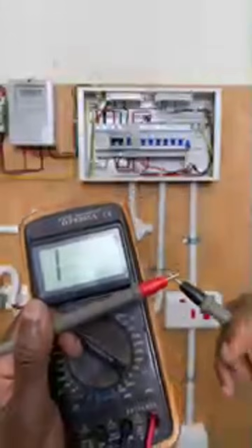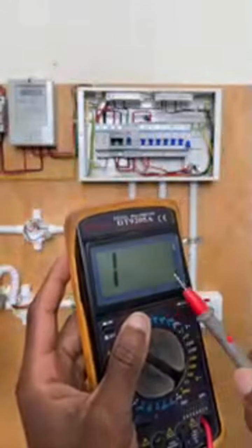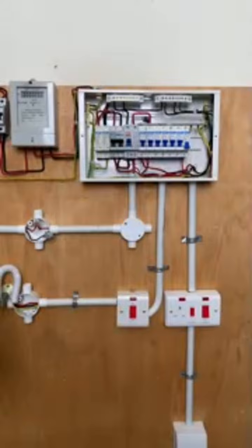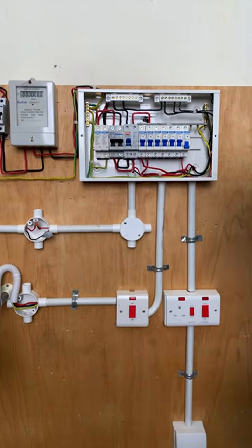A short circuit is detected this way. It is actually a measure of resistance. So if you place the probes together, you expect that beeping sound. Most likely you will see zeros here or a very small number, meaning that there's a problem. It is like doing this, my top boss. It is like taking a wire, you know. Is it a wire or is it a cable? It's like taking a wire such as this one.